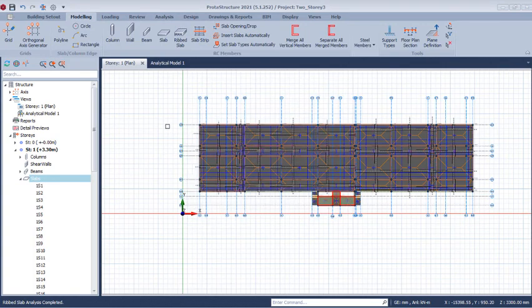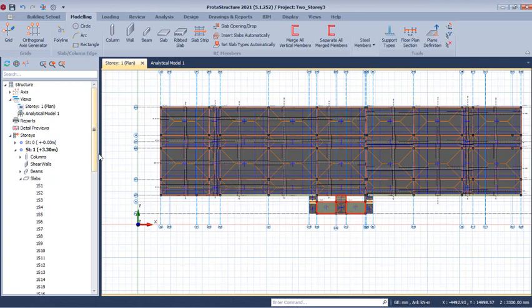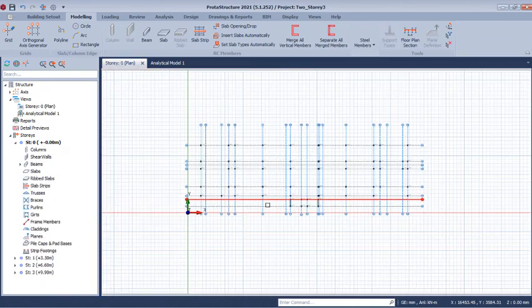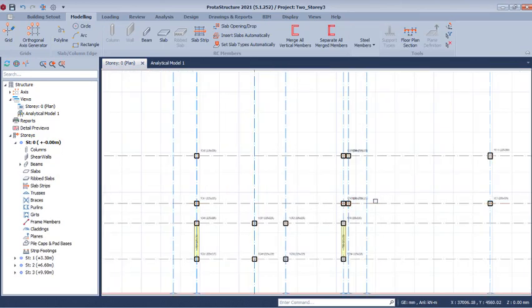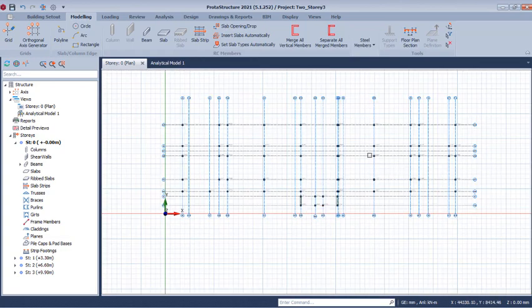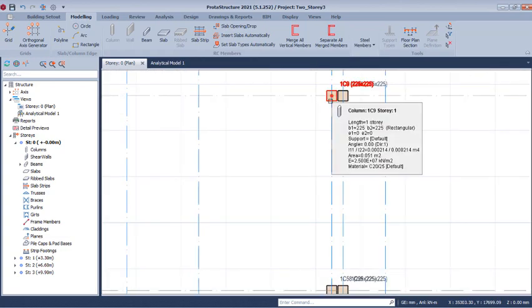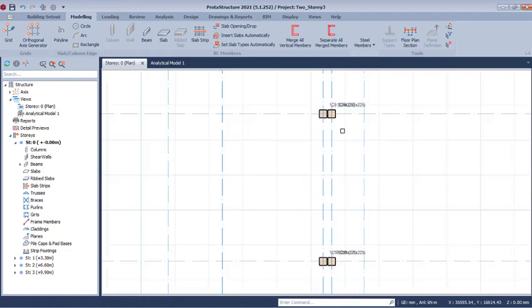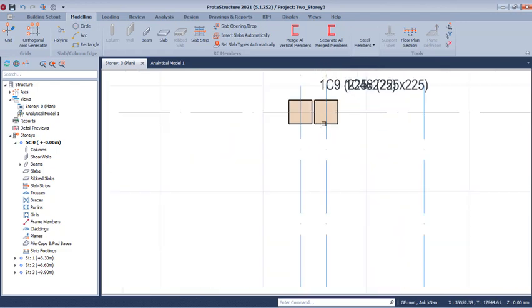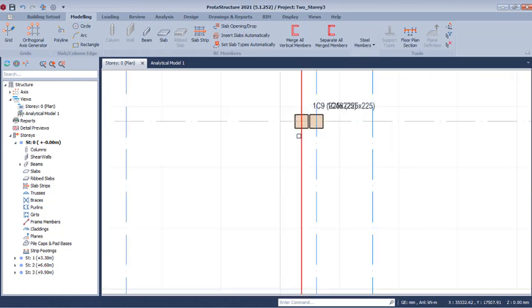All right, so the next thing we will be looking at is the foundation design. For us to design our foundations, we need to navigate to story 0 right there, where we see the columns here. So for these columns, the ones that are combined footings, they are going to be combined at the foundation here. So this one that has an expansion joint, we are going to combine it. You get the two selected like this, right click, and then click on insert combined footings. You can select that, and then give the program some seconds to load the foundation design dialog options.